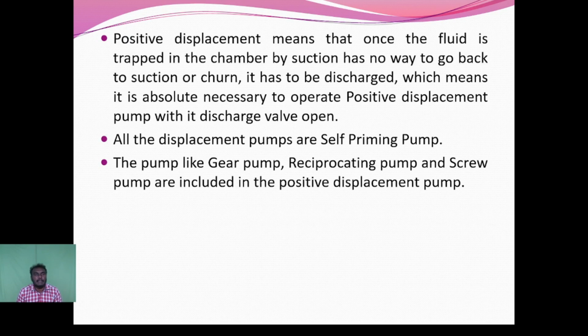Positive displacement means that once the fluid is trapped in the chamber by suction, it has no way to go back to the suction. It has to be discharged, which means it is absolutely necessary to operate a positive displacement pump with the discharge valve open.